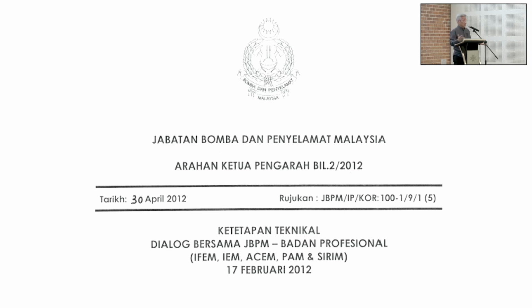Car parking, storage. What's the volume limit of storage? It's only 5,500 cubic meters. You put in sprinklers, it's only 11,000 cubic meters. For a flatted factory, most times it's too small.